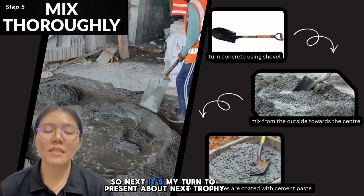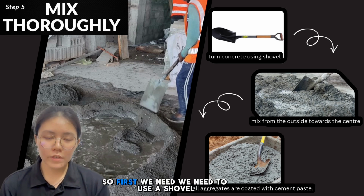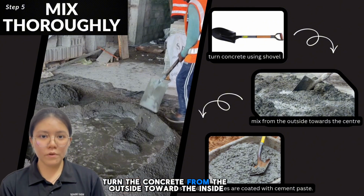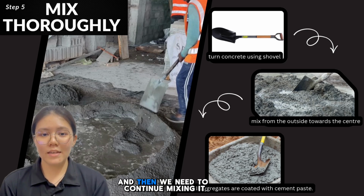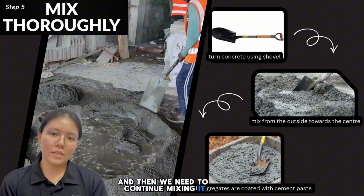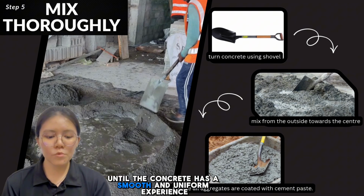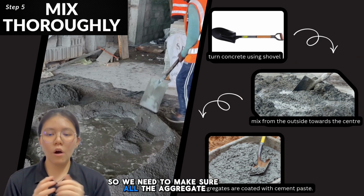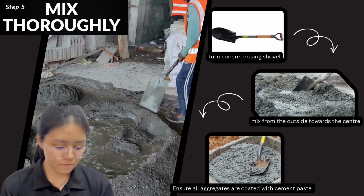Next, it's my turn to present the mixing flow. First, we need to use a shovel to turn the concrete from the outside toward the inside, toward the center, and then continue mixing it for about 3 to 5 minutes until the concrete has a smooth and uniform appearance. We need to make sure all the aggregate is fully coated with cement paste.